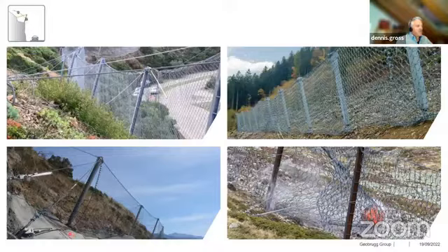are carried. And on the lateral parts of the barrier, you can see here some braking elements, which are also anchored into the subsurface. In case of an impact, like you can see it here on the right-hand side, the deflection of the mesh and then consequently the pull on these support ropes will be dissipated through these brake elements into the subsurface.